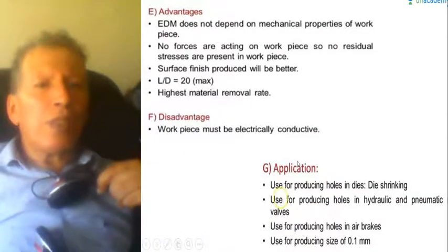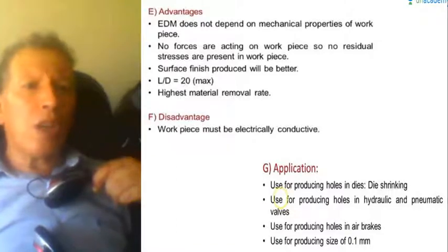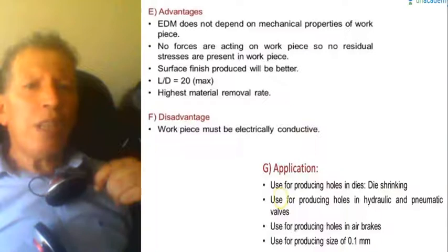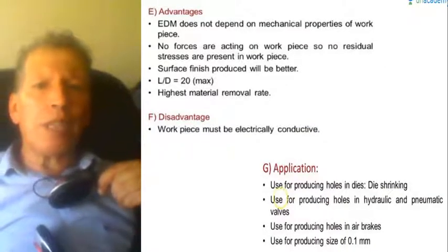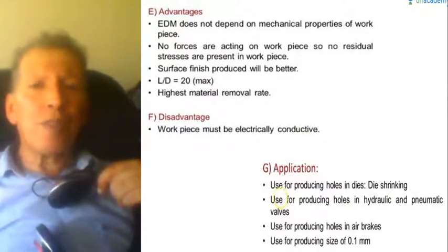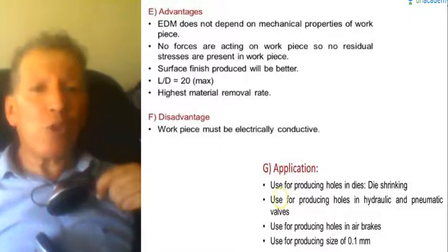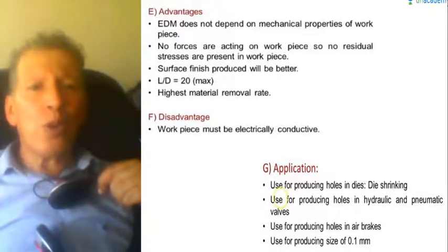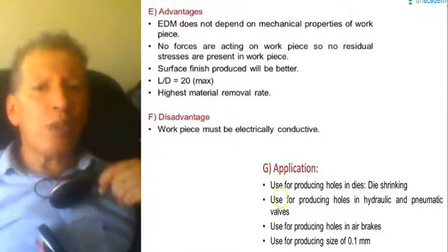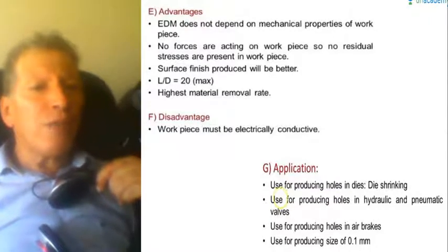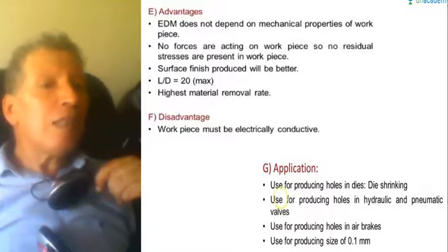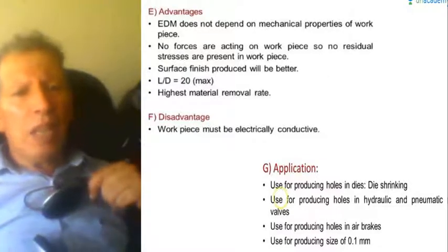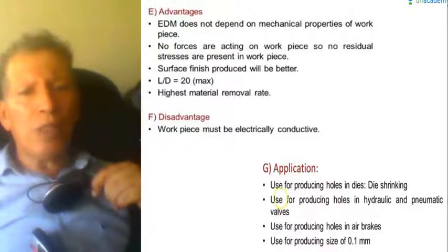What are the advantages of electric discharge cutting, electric discharge machining? It does not depend on mechanical properties of the workpiece. So it's the electricity that does the whole job. No forces are acting on the workpiece, so no residual stresses are present in the workpiece. The surface finish produced will be better, so it's better quality. The edge is better. The highest material removal rate.